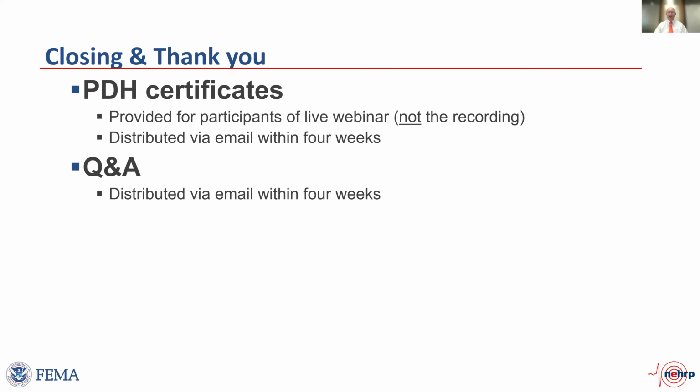And when we did those designs, we found that some of those designs with the modal method actually had worse collapse performance than the methods from ELF. So the conservatism of the ELF helped the system out. And it's unlikely that code writers are going to prohibit the use of modal response spectrum analysis, of a more complex form of analysis. But we certainly shouldn't prohibit the simple conservative method.